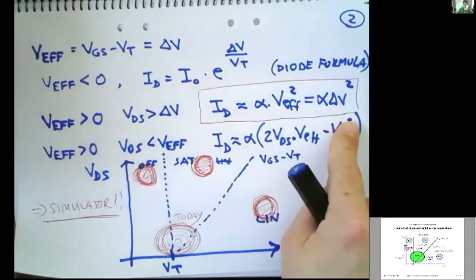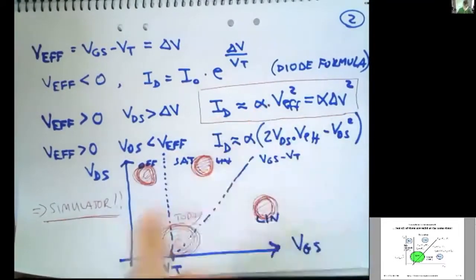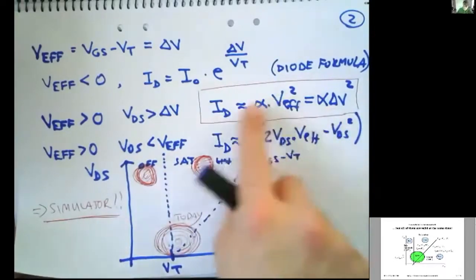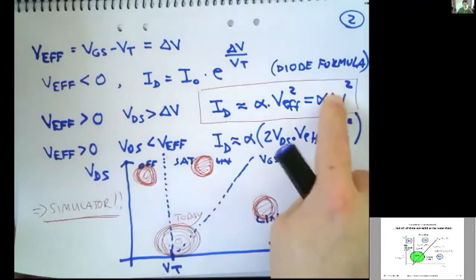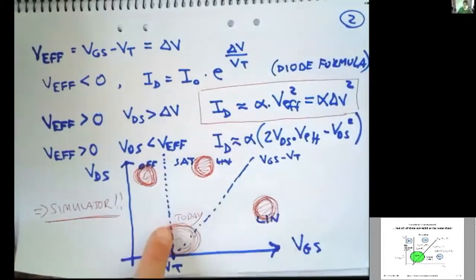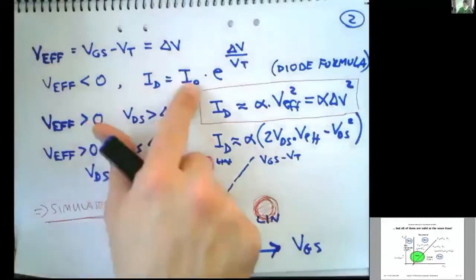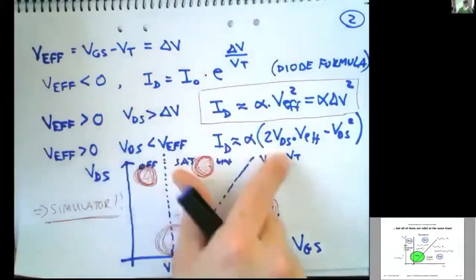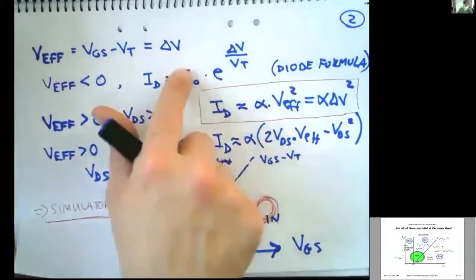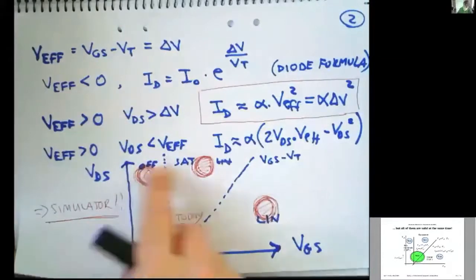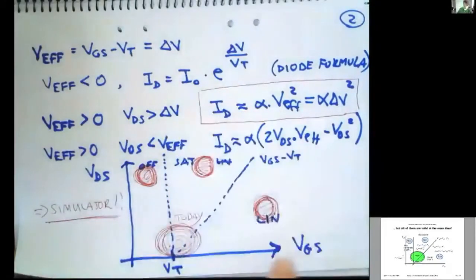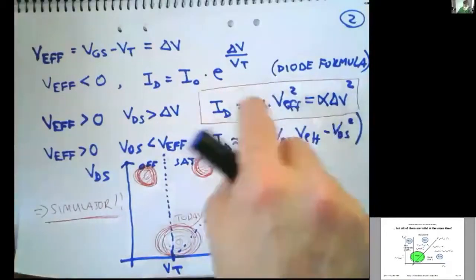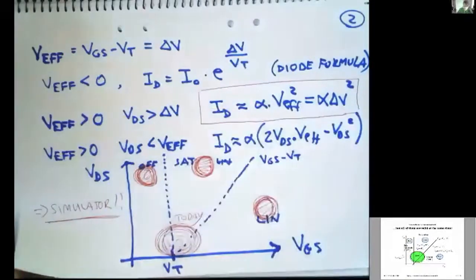All right, so the outcome was that we would look at the saturation region, this very simple formula, to be honest. It's just a current equal to a constant times some voltage squared. We observe that we will be running around in many different operating regions here, and there is obviously some sort of soft combination of these three equations. These three equations were the old extreme ones, far off on the edges here. They have been with us for the last 40 years, and they will continue to be, just because they are easier to work with.